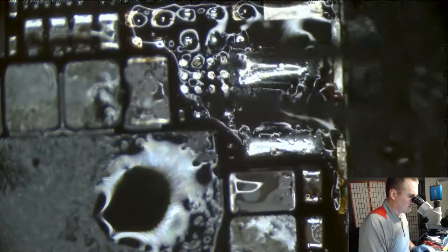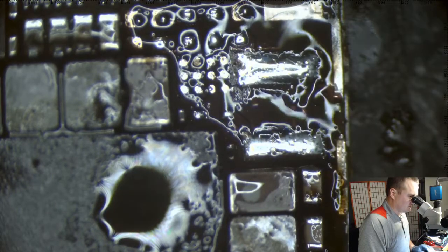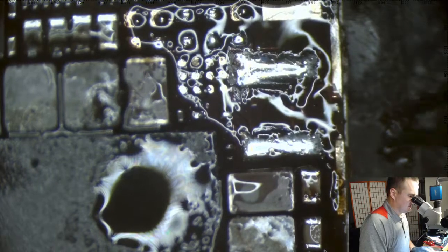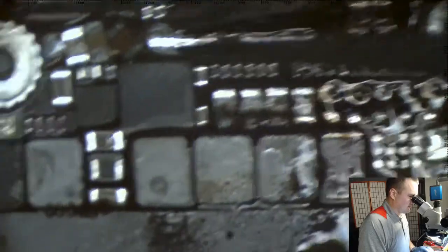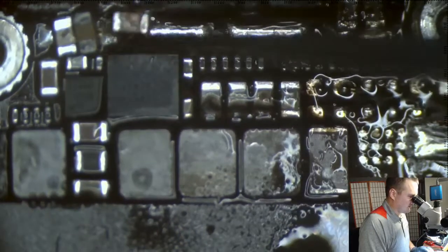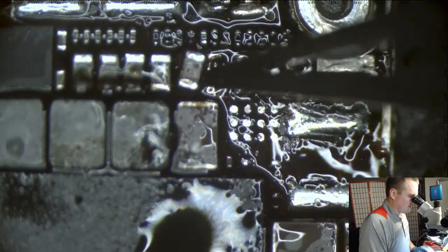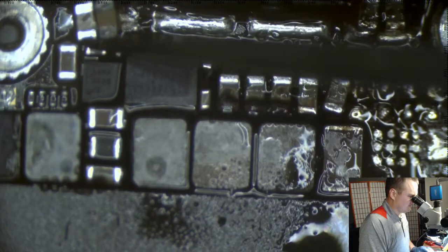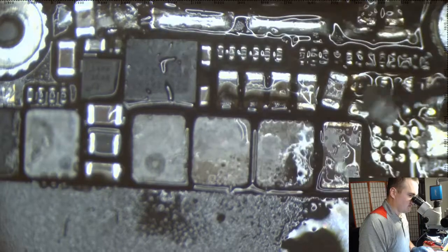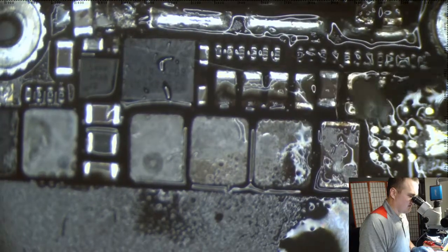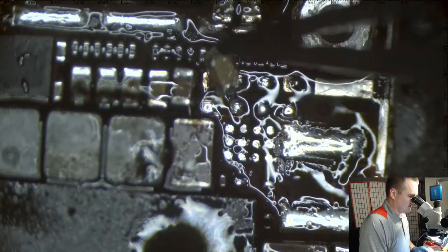Not all of this, but you know, pulled the cap, replaced a diode and a boost driver, left everything else. Sure enough, phone power's on, backlight comes on, victory. I'm sitting there messing with it, just reveling in my own awesomeness. And I notice, sure enough, this backlight's not that bright. Shouldn't it get brighter than this?